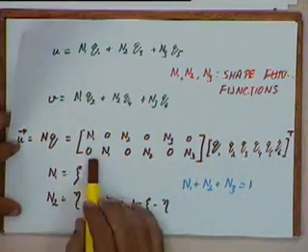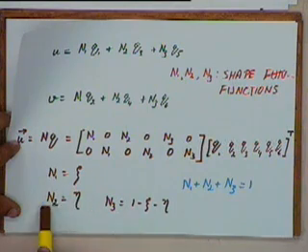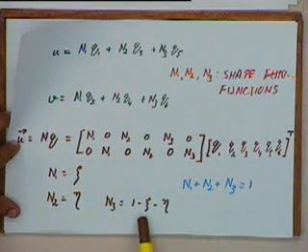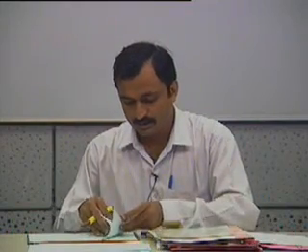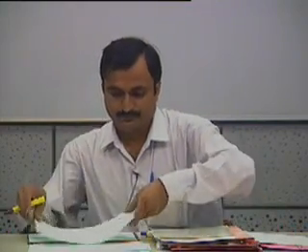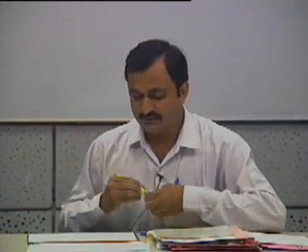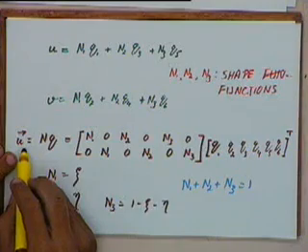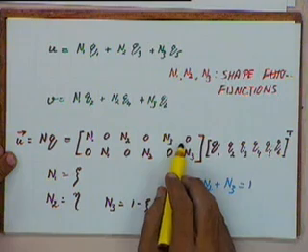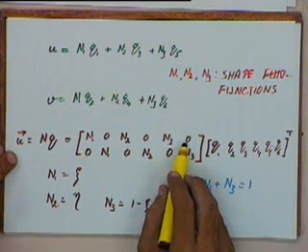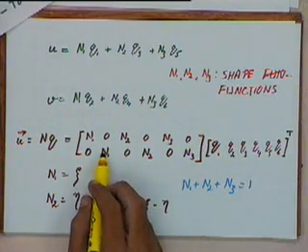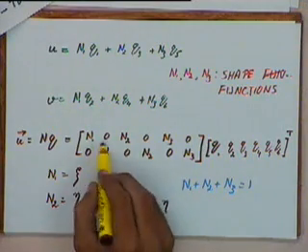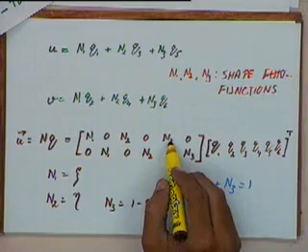So we will get u to be given by this expression where n1 is zeta, n2 is eta, and n3 is 1 minus zeta minus eta. Now, right now what we have done is that we have given an expression for u as a function of n1, n2 and n3. But we haven't yet specified which point we are talking of. We haven't yet related n1, n2 and n3 with the x values.